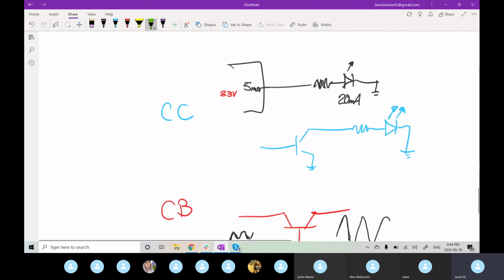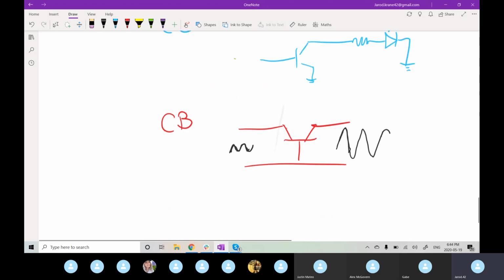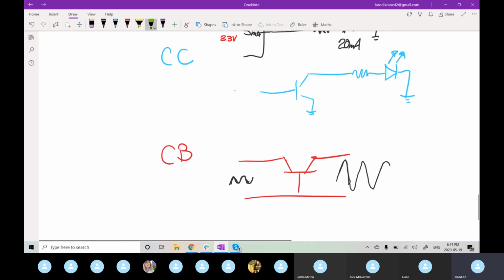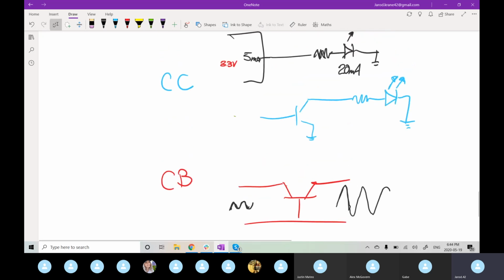So you're able to swap it in, do a common emitter to achieve the same thing here, slight configuration change, or do a common emitter on this one, because again, it can do either voltage gain or current gain. So it has the same functionality as both of these. It can do both of these simultaneously.